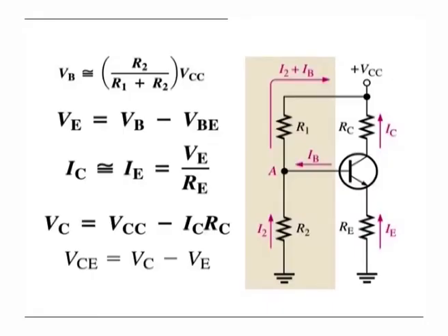The basic analysis developed in this example is all that is needed for most voltage divider circuits, but there may be cases where you need to analyze the circuit with more accuracy. Ideally, a voltage divider circuit is stiff, which means that the transistor does not appear as a significant load.